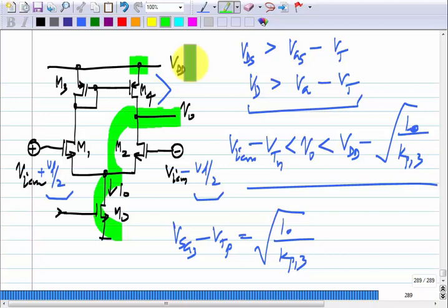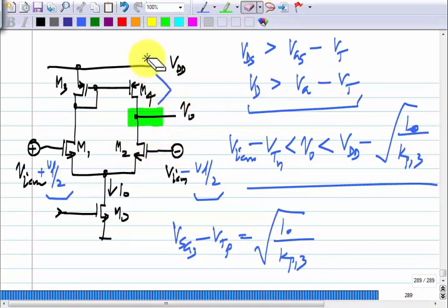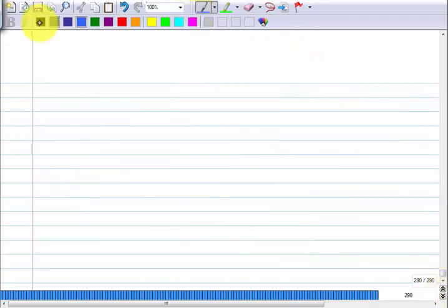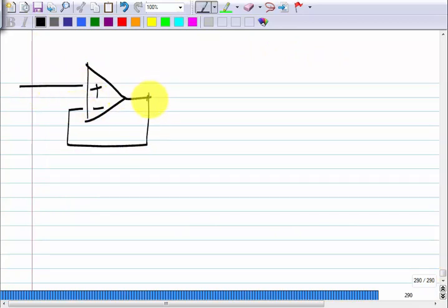Okay. So, now we have the swing limits on the input common mode voltage and the total output voltage. Okay. And this we can use to calculate the swing limit of any other circuit we make with it. Let us take the example that we took earlier. This is a unity gain buffer made using this op amp. Okay. I will call the input bias Vi0 in order to not confuse notation. In the operating point, what will be the output? It will be Vi0, right.